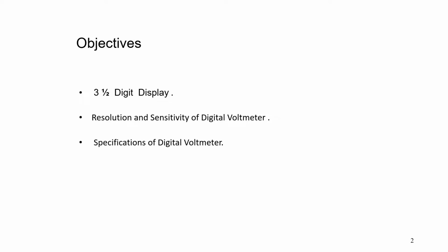The sample rate multivibrator determines the rate of the measurement cycle. A typical value is 5 measuring cycles per second with an accuracy of plus or minus 0.005% of the reading. The sample rate circuit provides an initiating pulse for the ramp generator to start its next ramp voltage. At the same time, a reset pulse is generated, which resets the counter to the zero state.